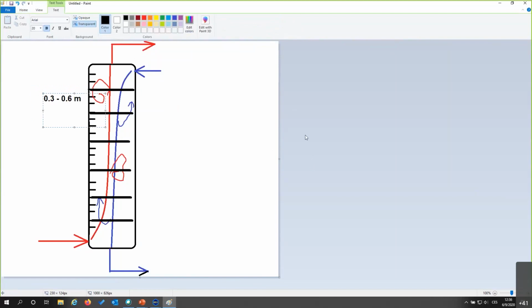One thing that might be abstract and hard for you to evaluate is how much safety margin I actually have within this recommendation. Generally, if you are using a value closer to 0.3, that means that you are less conservative. If you want to be more conservative, you would use taller increments, so you would be closer to 0.6 meters.